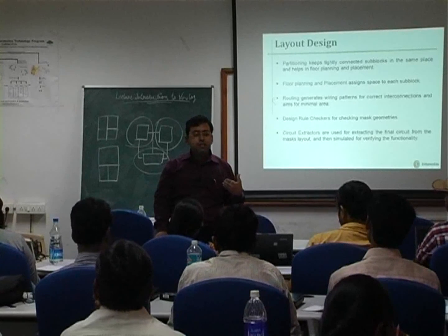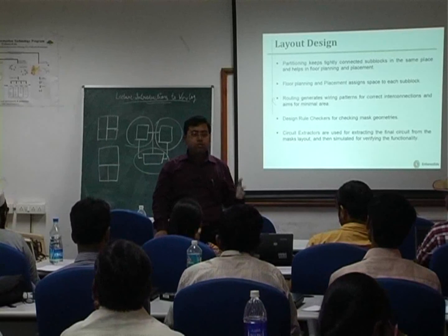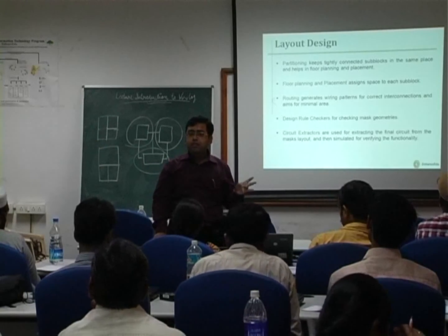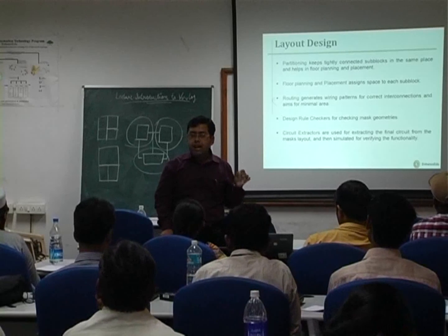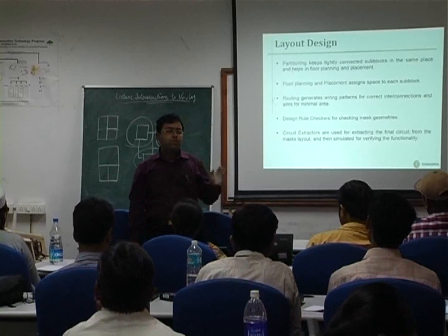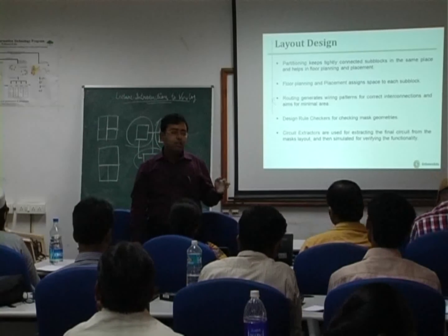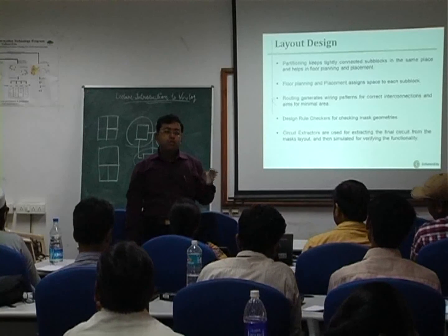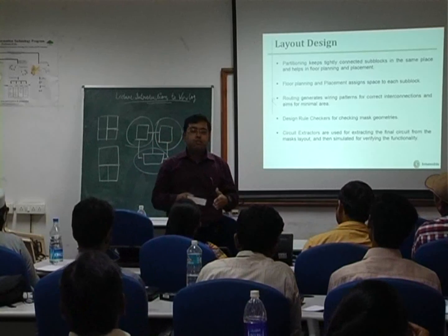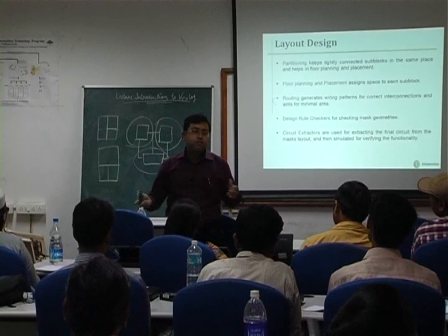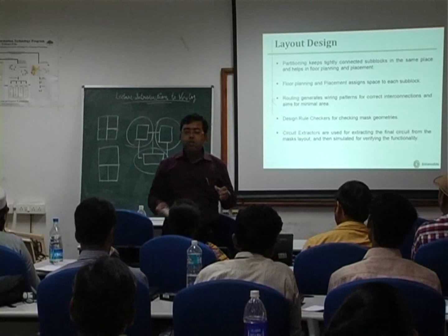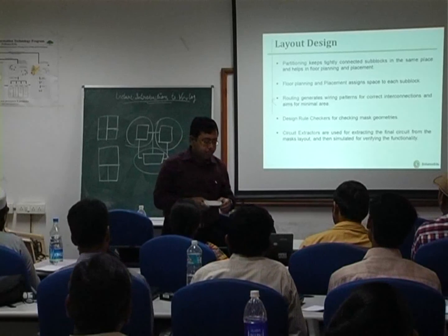However, our requirement is that the results should correspond to the initial simulation results over a certain error spectrum, and that's why after we do the layout design, after we do the post layout simulation verification, we check whether the initial schematic corresponds to the layout or not. That is what we mean by layout versus schematic verification, or LVS.